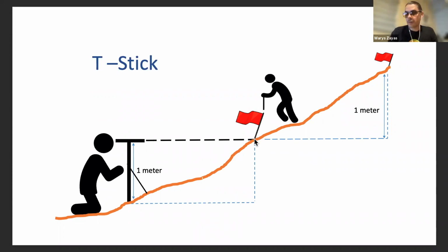That's the upper part of our slope, or not the upper part of our slope. It is the point where we want to start our erosion barriers, or our crop lines, right? So we set that point there because it's the point of reference in the area where we want to start to measure to place our erosion control barriers. You start to work, you stop here and look through the side, and you say, oh, okay, no, I saw the point at level 0 here, so I know that I need to keep walking down the slope.